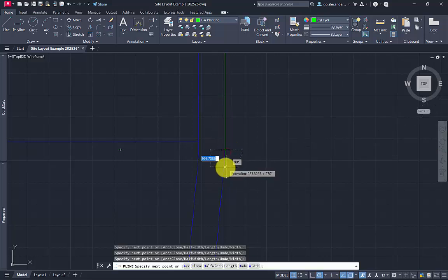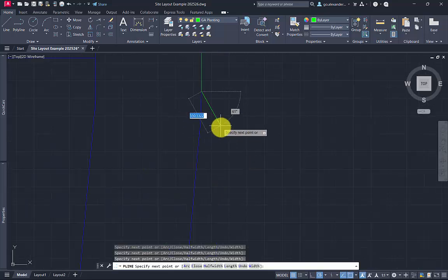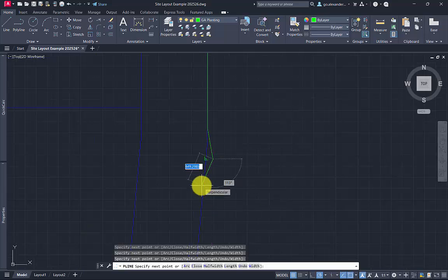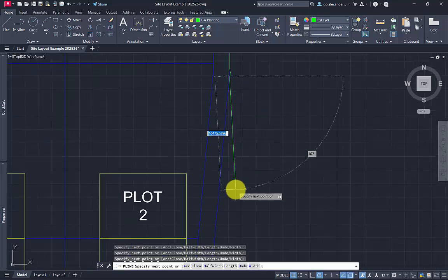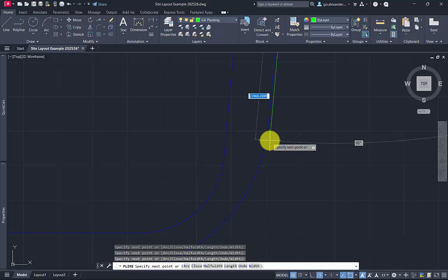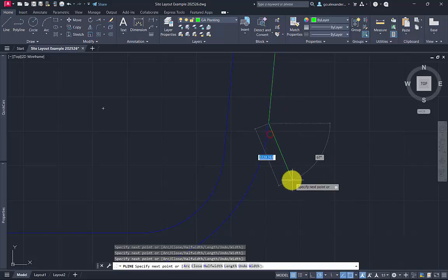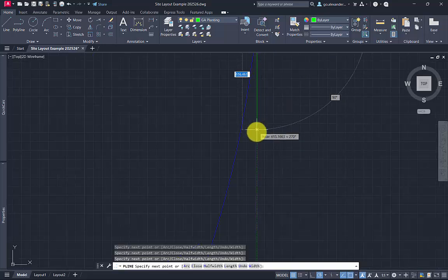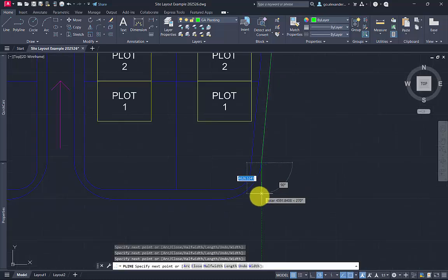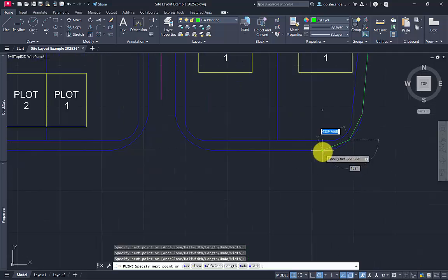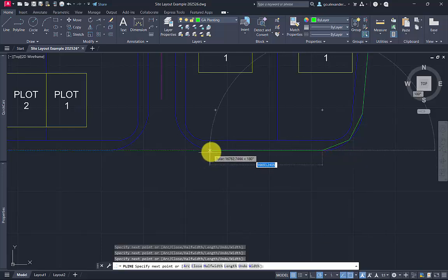So really here we have, I'm really doing this on purpose just to show that drawing the line over the top of what we have is not the correct thing to do. This is what some people have done in the past. So you could go to there and then sort of try and choose points in between. It's really quite tricky. The better thing to do is use existing lines and take a copy of them and create a full boundary line. I can always demonstrate that in a bit more detail at a later stage.